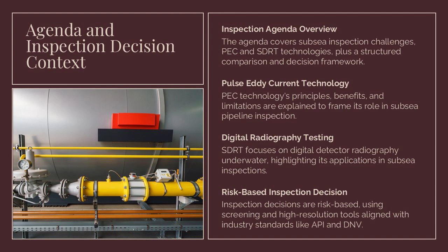From a speaker perspective, it is important to emphasize that subsea inspection decisions are rarely binary. The inspection objective, whether screening, defect characterization, or acceptance, drives the method selection. This agenda reflects a risk-based inspection, RBI, mindset consistent with API and DNV philosophies, where screening tools are used to identify suspect areas and higher resolution techniques are deployed selectively. The audience should understand early that the comparison is structured to support lifecycle integrity management rather than one-off inspection activities.